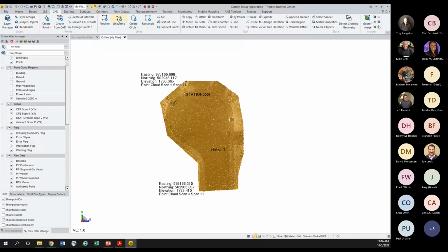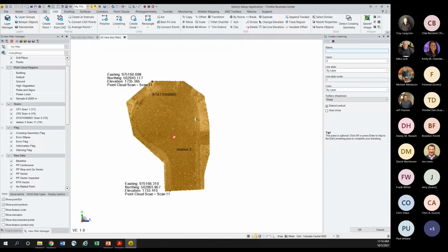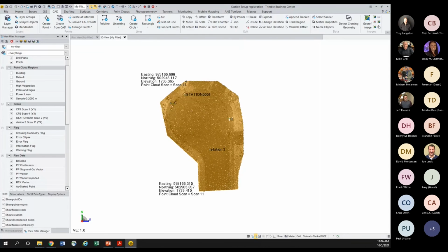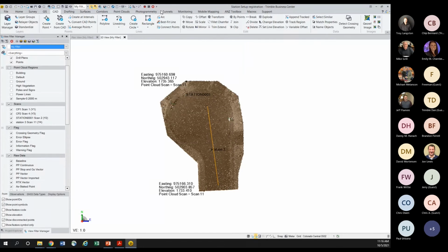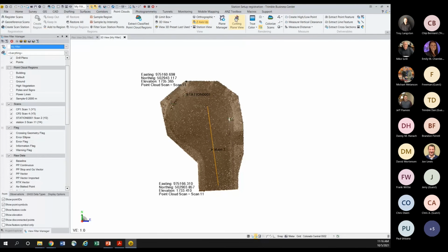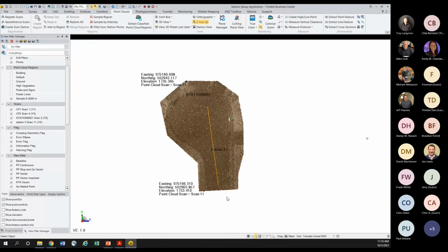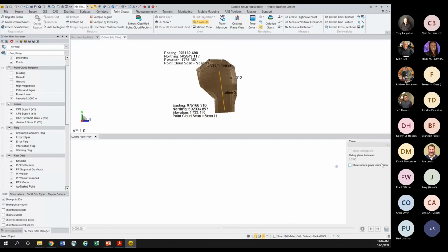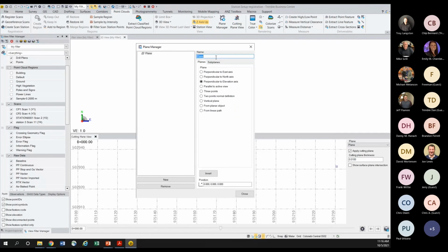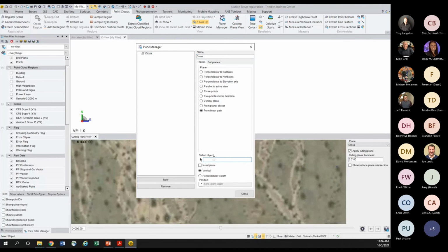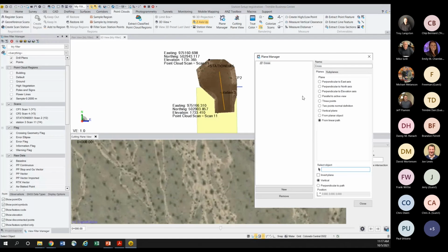is if you wanted to get some slices out of here, there's 100 ways to do it. I can go ahead and just draw a line like this here. I have this line, and you can go up into the point clouds and create these cutting views along a trajectory. What this will do is I can say new, cross section, from a linear path. Then all I have to do is select the line.